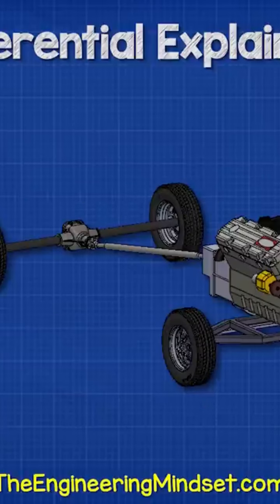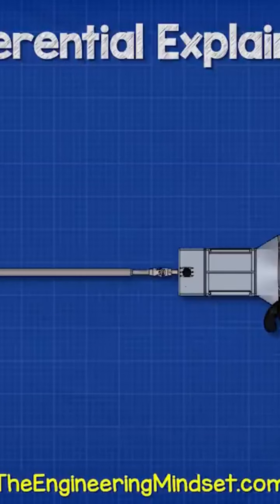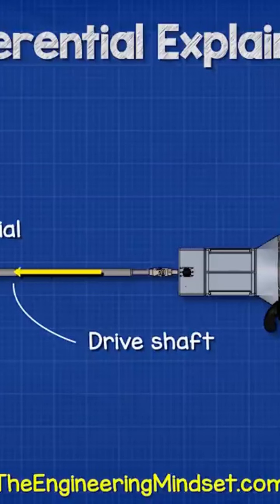When a car moves in a straight line, the engine provides power through the drive shaft into the differential, which divides the power between the two rear wheels. This propels the car along, and so the wheels will all rotate at the same time at the same speed.